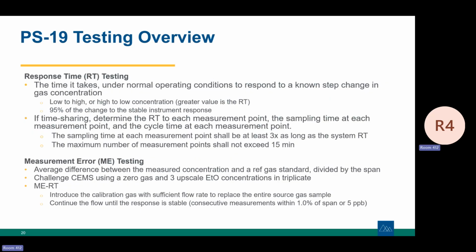Sorry, I know this is a lot of words I'm trying to summarize. Response time testing is looking at the time it takes to do that step change, either from low to high or high to low, to get back to a stable state. Whichever is the greater of those steps is going to be your response time. I think this is especially important, as we've seen, if you're time sharing these sample points to get those multiple points within the 15-minute period. You need to make sure that the response time is sufficient, because the measurement time shall be at least 3 times as long as the response time.